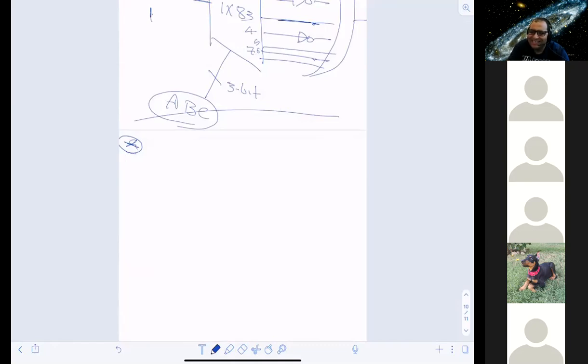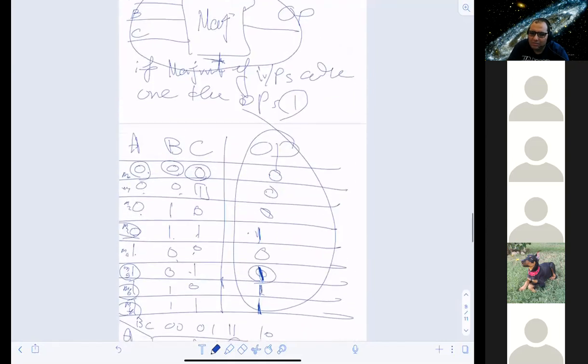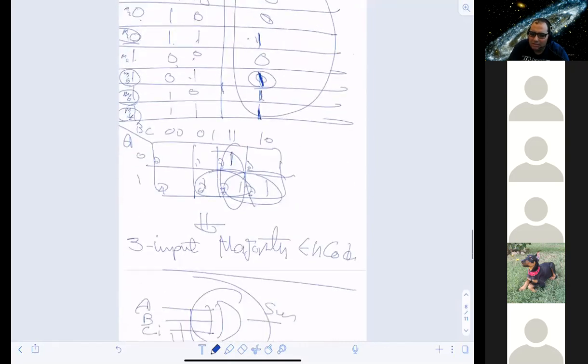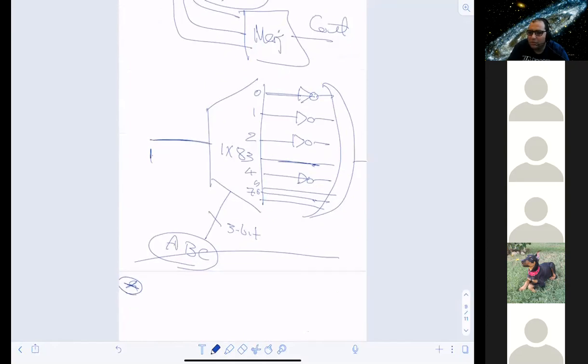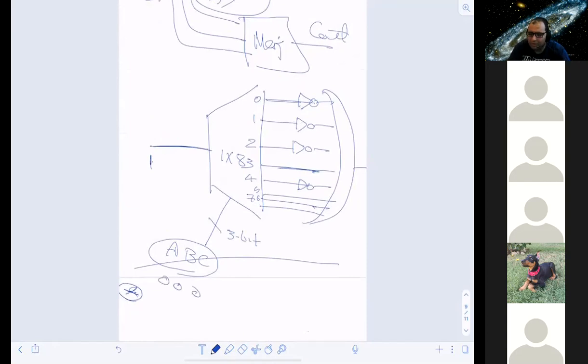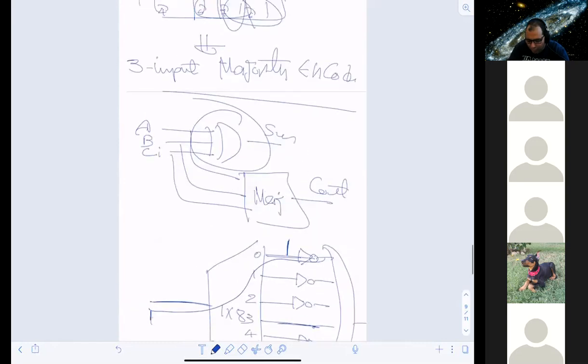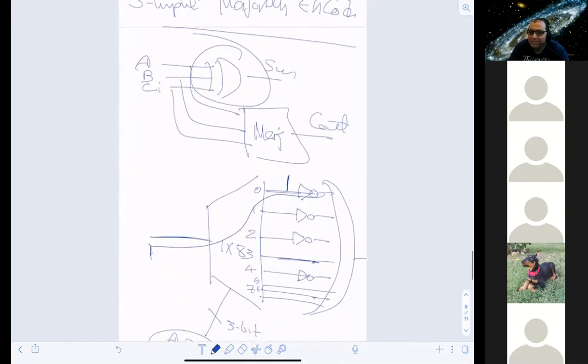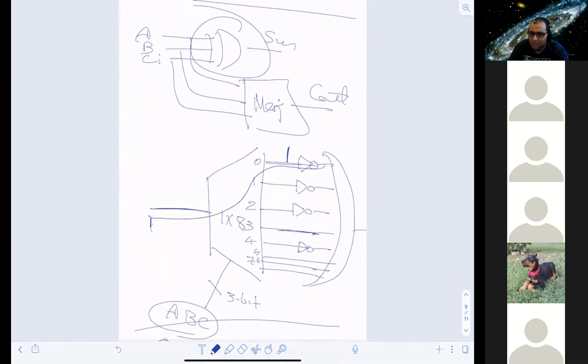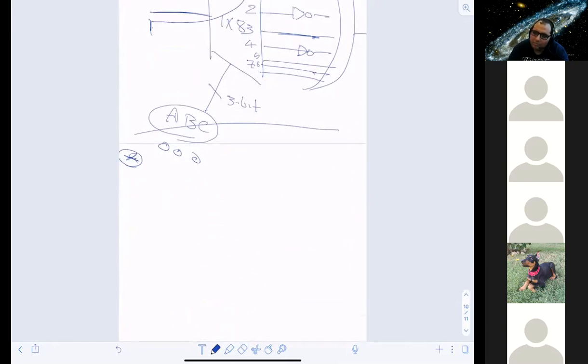Can we go back to the diagram? Why are you adding NOT gates in front of some of the outputs? You mean here? Yes. Okay, if ABC is 0, 0, 0, what will happen? The output is going to be 0. That means this one will go here, so it's going to be 1, but I don't want it to be 1. I want it to be 0. Exactly. So you can do this with any bits, with C, or BC, or anything you want. Any other questions?